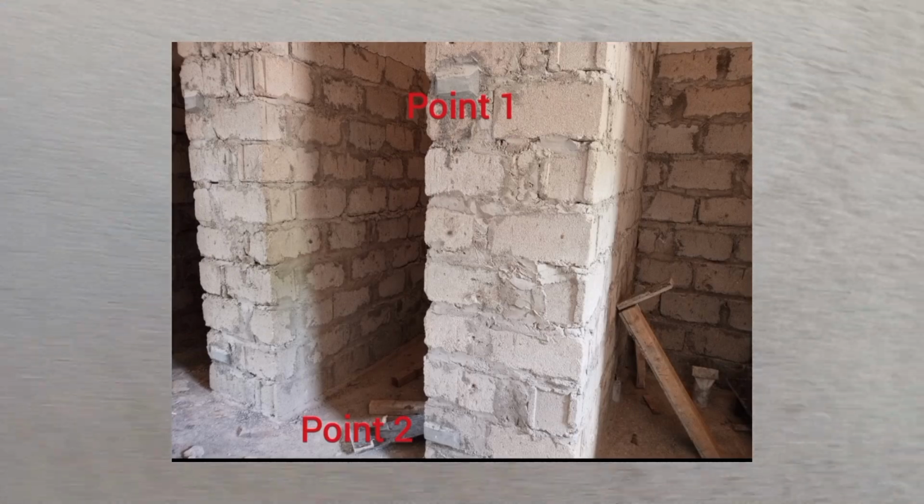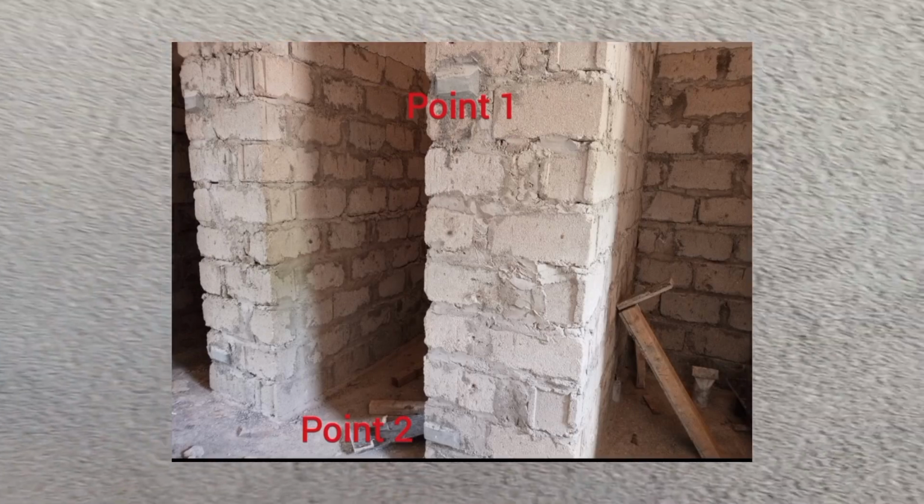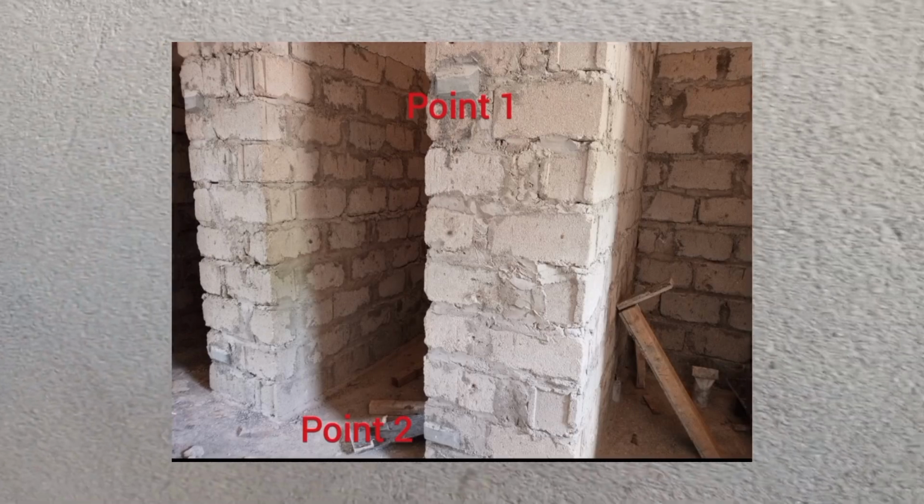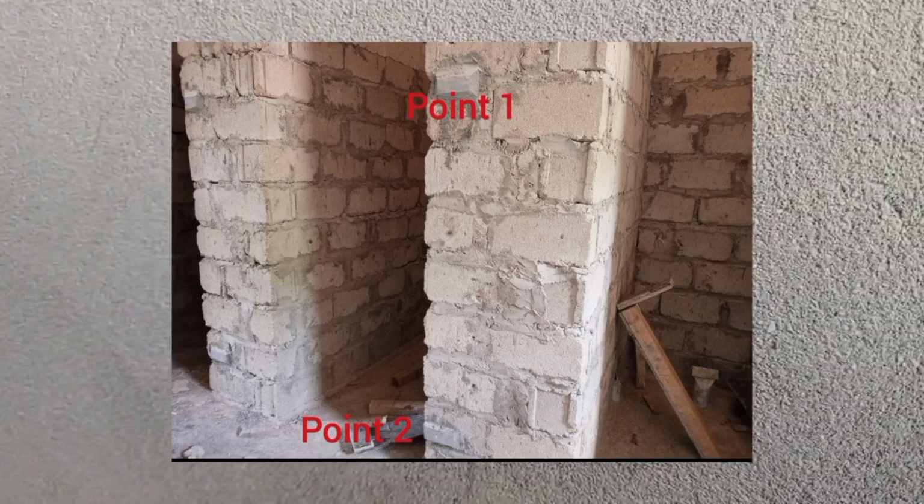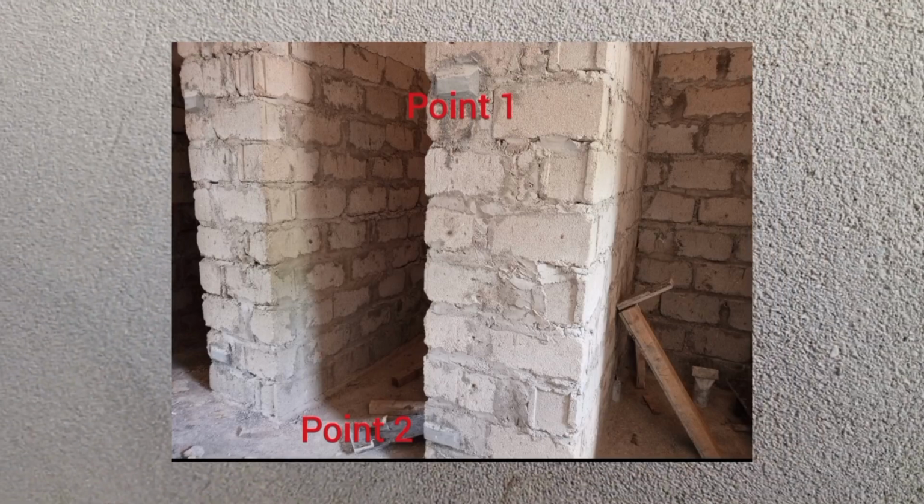Remember these points that you will do on the wall using the cement sand mortar. These points will be equivalent to the thickness of the plaster that is required.